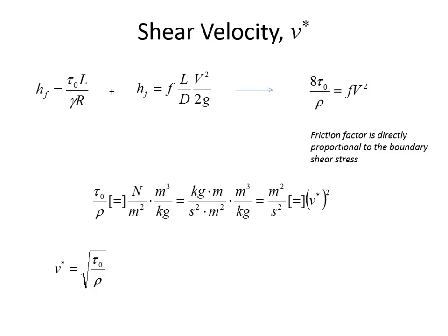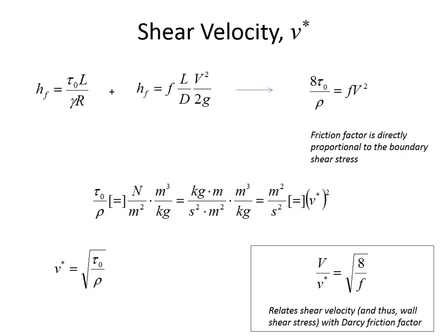So it's a dimensional analysis thing, really, just rearranging the units until a parameter you're interested in is being expressed as a velocity, an equivalent velocity, rather than in terms of a force per unit area, as shear stress is. And so it's a way of accounting for the shape of the conduit, the fluid properties, and expressing the forces that are being applied in terms of a velocity, an equivalent velocity. That's sort of the long and short of what shear velocity is.